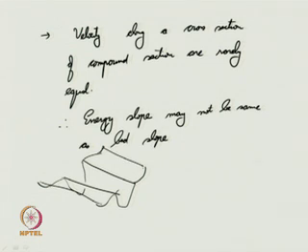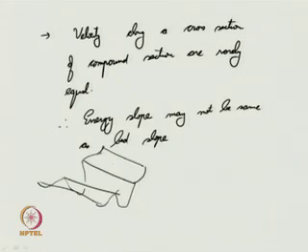So, in such a channel portion, along the flood plains or the side channel portions and all, you may have to incorporate different velocity. In the main body it will be a different velocity. Subsequently, along this entire reach, how much discharge is available from the flood plain as well as along the main body, the combined discharge, how to evaluate them.